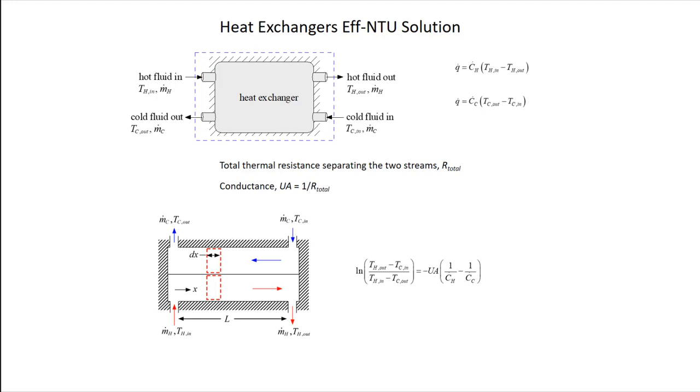Okay, so last time we started talking about heat exchangers, and specifically we talked about how if you want to get a solution for any specific configuration, you have to do differential energy balances on the two fluids, and then you get some coupled set of ordinary differential equations that have to be solved, and then you'll get ultimately a solution that when you couple with the energy balances and knowledge of the UA should be enough to actually solve your heat exchanger problem, right?